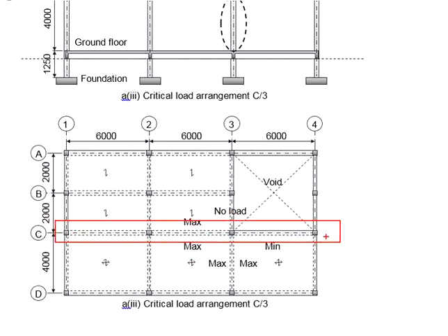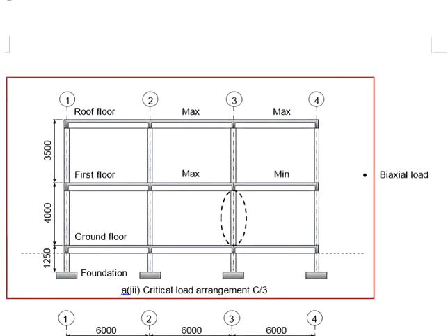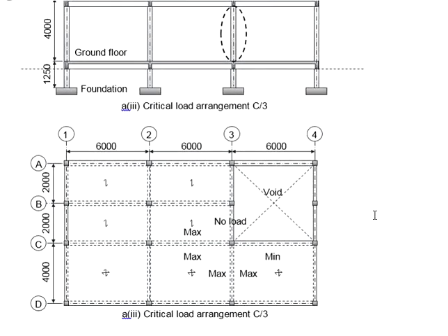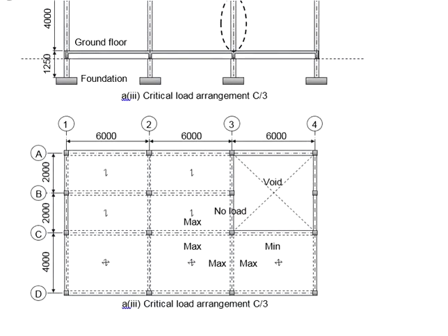Take this frame out. It should look something like this. We are talking about this column. Based on the distributions of the load, the one-way slab will have no loads distributed to this beam. You will assume half of the slab, the load will go to this side.